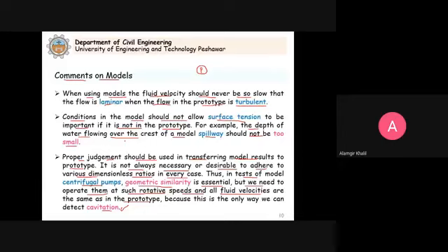So when we design or operate these, we have to make sure that cavitation does not occur. What is cavitation? As the fluid passes through these machines there is an increase and decrease in pressure, and the pressure should not fall so low that the boiling point falls below the fluid temperature.